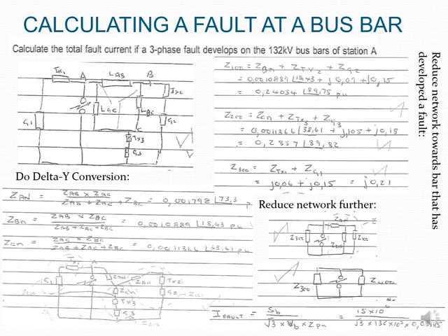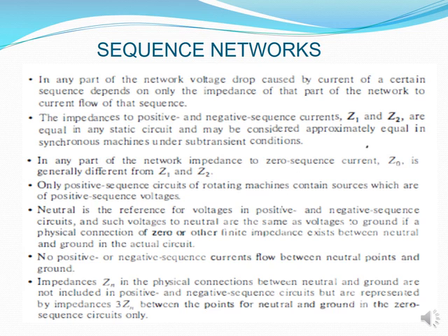So therefore, I can then work out my Z per unit Thevenin equivalent of the parallel two, and then for my fault I simply go and substitute into the formula that says SB over square root of 3 VP times my Z per unit, which will be my total Thevenin Z per unit. So what we're looking at now was if we had a balanced fault occurring.